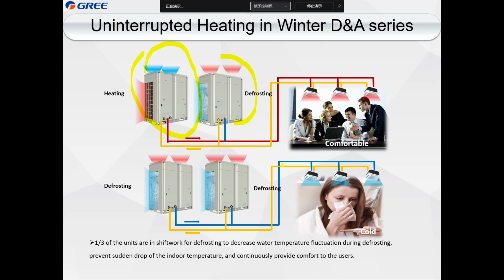This is not like the VRF, GMV. Once the outdoor unit enters into defrost mode, all the indoor units will stop. So this feature of the modular is uninterrupted heating.